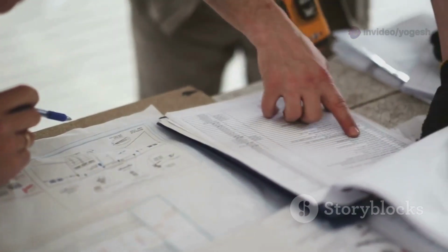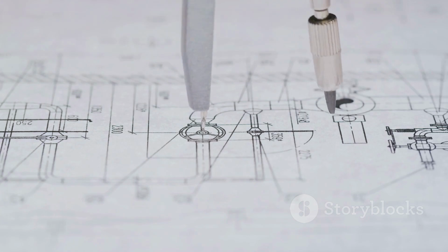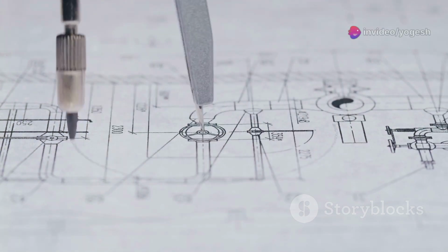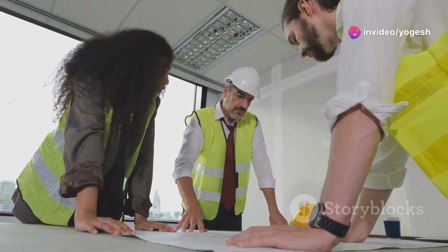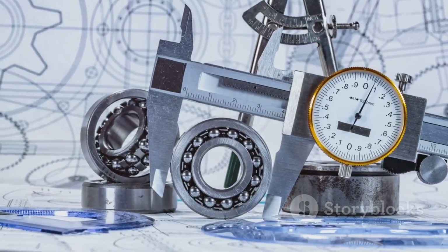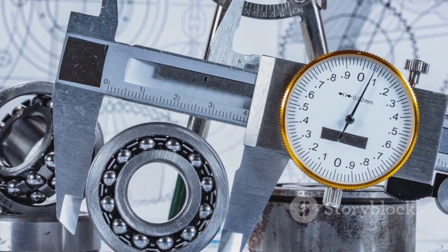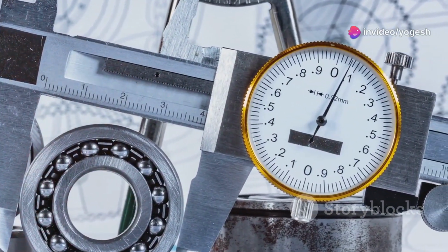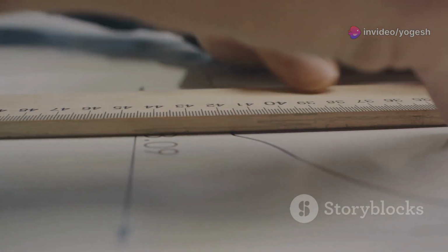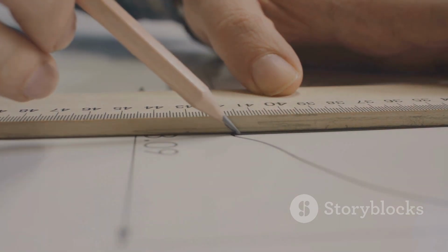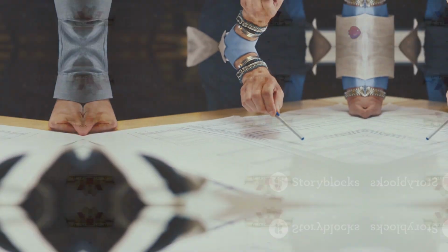Tip number 4 is crucial. Always adhere to industry-recognized drawing standards. Think of these standards as the grammar rules of technical drawings. They ensure that your drawings are universally understood, no matter where in the world they end up. Standards like ASME Y14.5 in the US or ISO 2768 internationally provide guidelines for everything from drawing layout to symbol usage. By following these standards, you create a drawing that's consistent, professional, and easily interpreted. Stick to the established standards to ensure your drawings are clear and unambiguous.